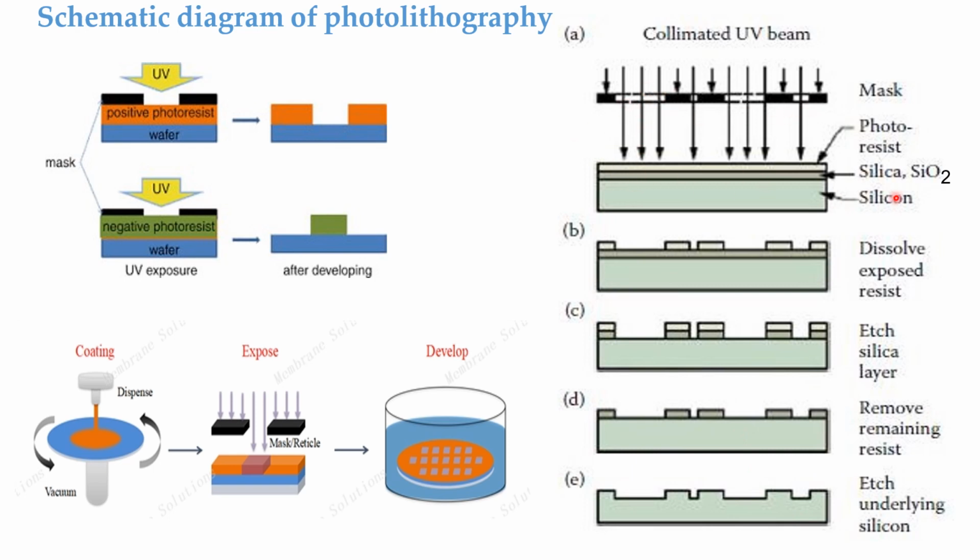First we have to put a photoresist layer on top of this silicon oxide, and then the mask, and then using the UV beam the photoresist gets soft if it is positive. There are positive photoresist and negative photoresist.